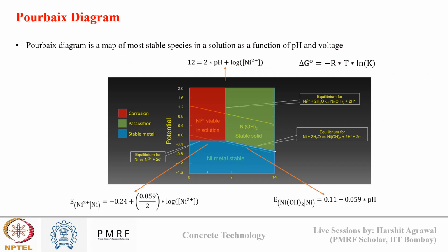And which oxidation reaction will happen, and which reduction reaction will happen, will be governed by the pH of the system. So to tackle this, we have the Pourbaix diagram. The Pourbaix diagram represents, at different potential and at different pH, what reaction can occur at a metal-nonmetal interface.